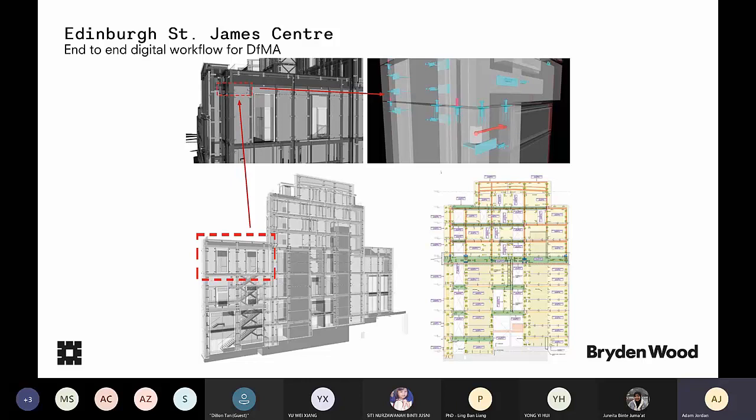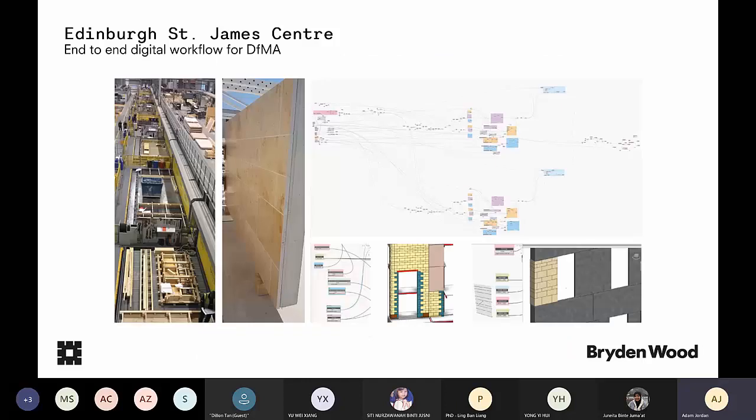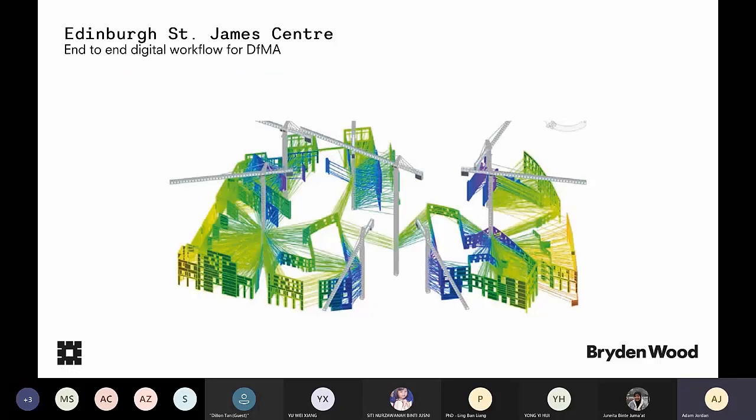So they had the data attached to them that defined it to a high level of detail, including all bracketry. And this became a real digital twin model, so structurally performing as it should. And then we used the model to schedule the components out directly for pricing and for procurement with the fabricator. So we used a bit of bespoke Dynamo scripting here to position stone panels across the facade. So 19,000 individual stone pieces at 10,000 square meters of stone, and all of them positioned according to the Dynamo rules, which were based on the architectural requirements from the concept design team of the project.